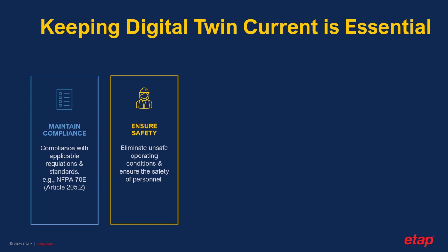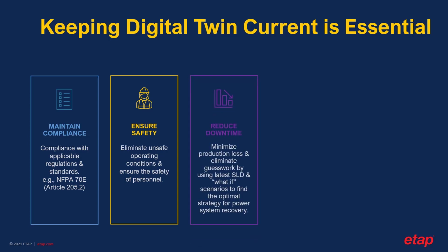The electrical safety studies and evaluations that we typically utilize the single line diagram for include calculations of short circuit currents, determining selective protection coordination or selectivity, assessing arc flash energy, evaluating the lockout tagouts and the interlocks, and therefore make it a very important document for ensuring safety.